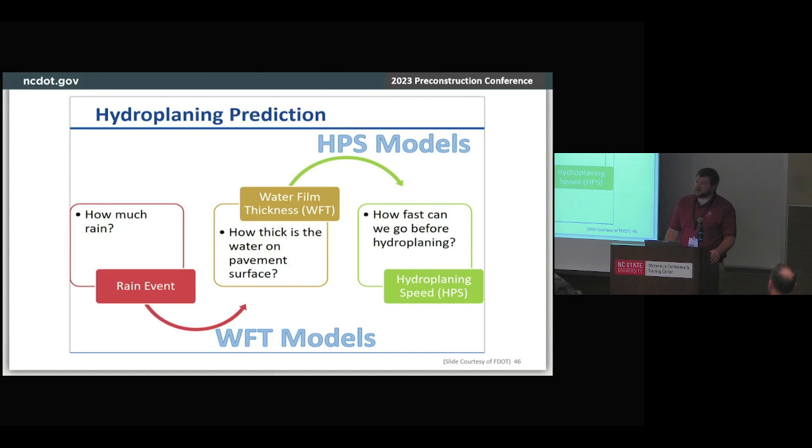It's so steep that the water path to travel across all the lanes and down the mountain is so long that you're seeing hydroplaning issues in the outside lanes in a 1 inch per hour event. But typically on most analyses, you're going to see hydroplaning occurring during the 2 inch per hour event, and that's going to be the majority of your controlling cases.